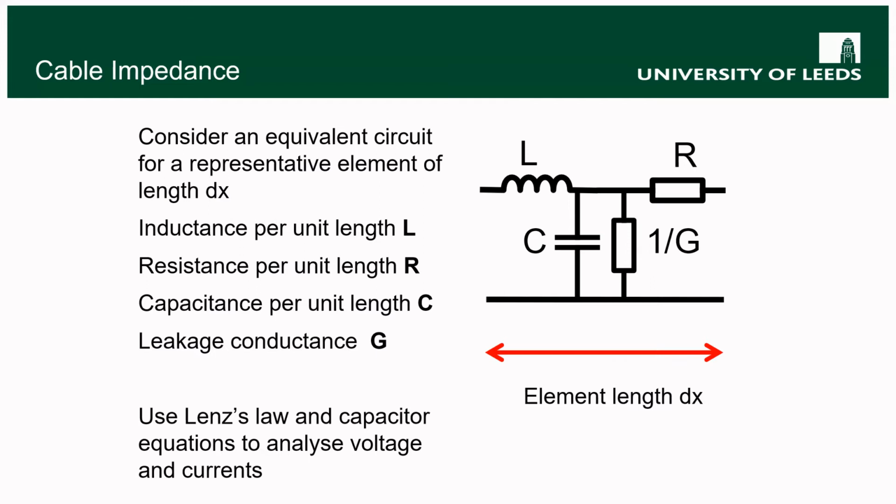You're going to end up with a capacitance between a signal line and a return conductor, like in the BNC or the triaxial cables, or between two cables if it's a pair of banana plug cables. You get some capacitance there, and you potentially get some leakage conductance as well. And so we can actually go and do an analysis of what's going on with these sorts of situations.